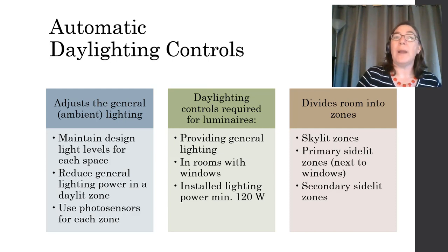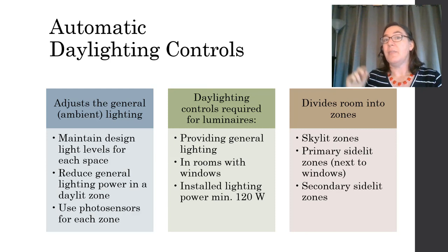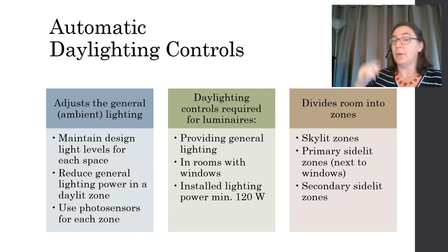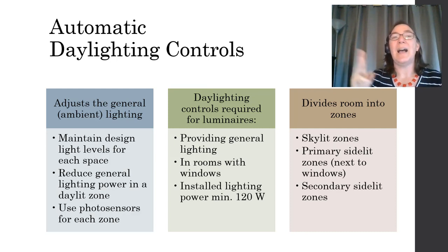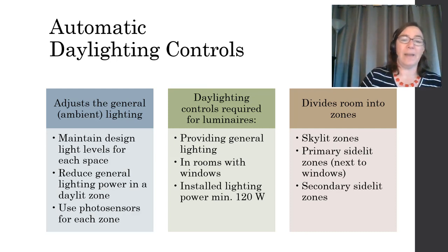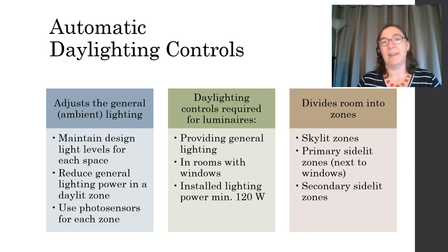Daylighting controls are required for all luminaires that are in these categories. They are providing general lighting, they're in rooms with windows, and there is a minimum of at least 120 watts of lighting. It's not very much, as you know.